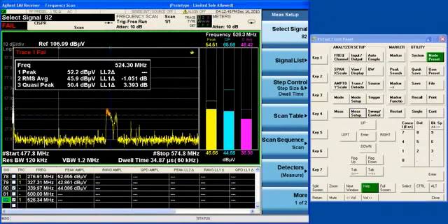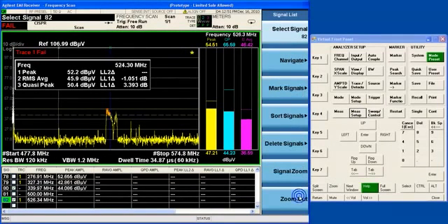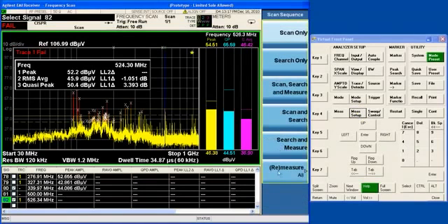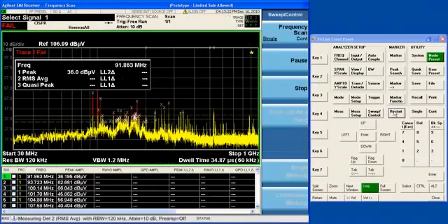Okay, now before I start the final measurement, I actually want to zoom out so that I'm looking at the full spectrum, and this will let me watch as I go from signal to signal and give me some sense of the progress of the final measurement. Now the measure window that you see here, the one that was used for measure at marker, is also used for the final measurement, just the way the same detectors are used for the final measurement. So now I can begin the final measurement. I'm going to select remeasure all again and restart the measurement.